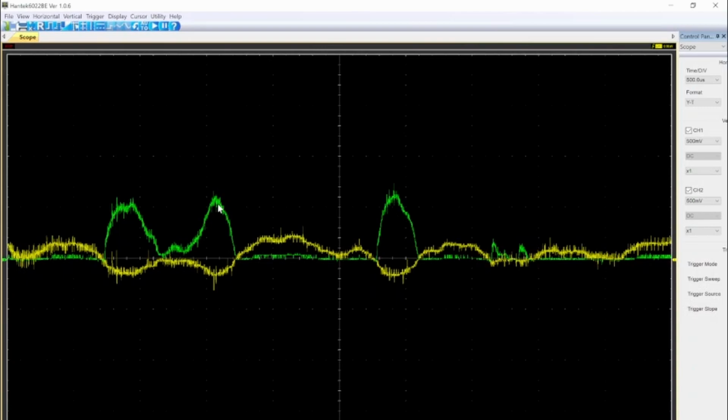That's what's happening here. But unfortunately, when the yellow signal goes above the white line, we're trying to times our 1 volt by -5, and we're trying to push out -5 volts. But because I've only got a single rail power supply and it's running off 5 volts and 0 volts, it's saturating it negatively, and as negative as it can go is 0 volts. So what's basically happening is we're chopping off half of our signal, and if you actually listen to the audio output instead of what I've dubbed over it for the video, you can kind of, in a way, hear half the song.